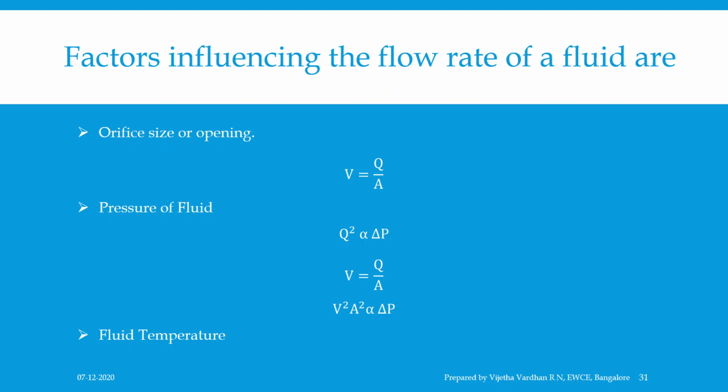Temperature of a flowing fluid increases due to external resistance to flow, sudden expansion and contraction in the passage, sudden change in direction, environment, and so on, which in turn influence the velocity of the actuator. If a conventional flow control valve is used to control the speed of an actuator, there is no compensation for change in temperature, and such valves are also called non-compensated flow valves.